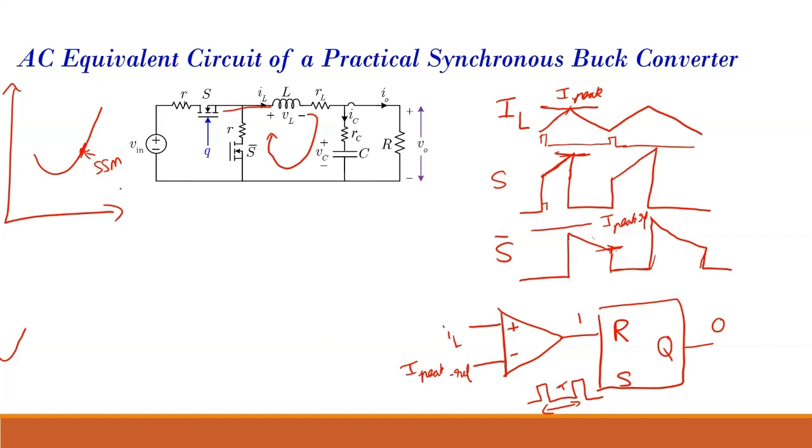Okay. Usually you are designing your converter, it has a particular rated operating mode of operation. So around that operating point, we will design the small signal model. We will linearize the model and we will use that small signal model for our analysis. And it could be that it will deviate from the actual operating point around which we have designed it.